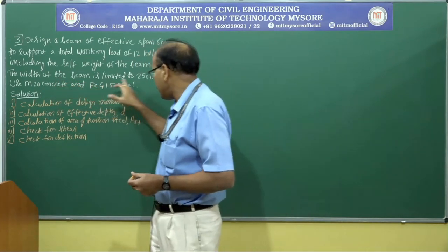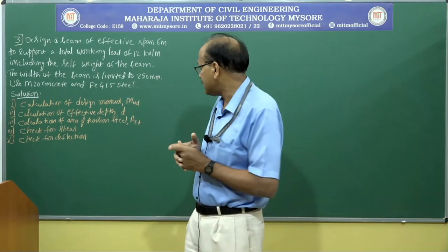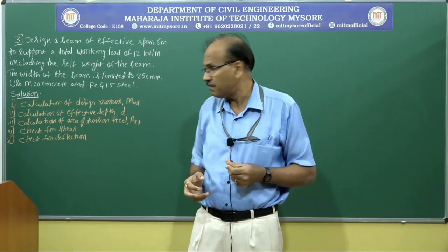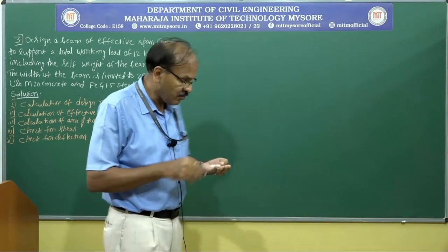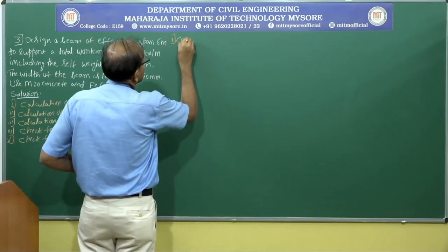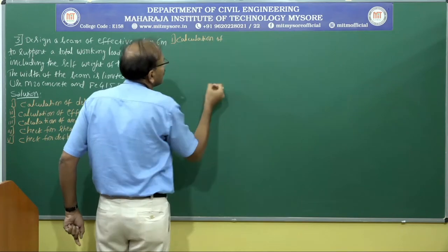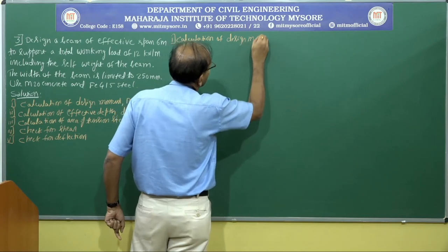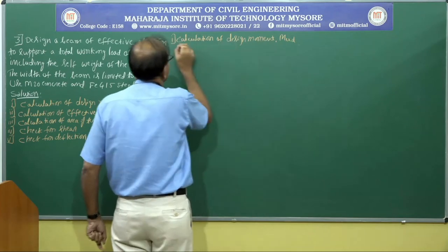So the width of the beam is limited to 250 millimeter. The width of the beam is fixed. We cannot change it. Use M20 concrete and Fe 415 steel. So let me go with the first step. Calculation of design moment, MUD.